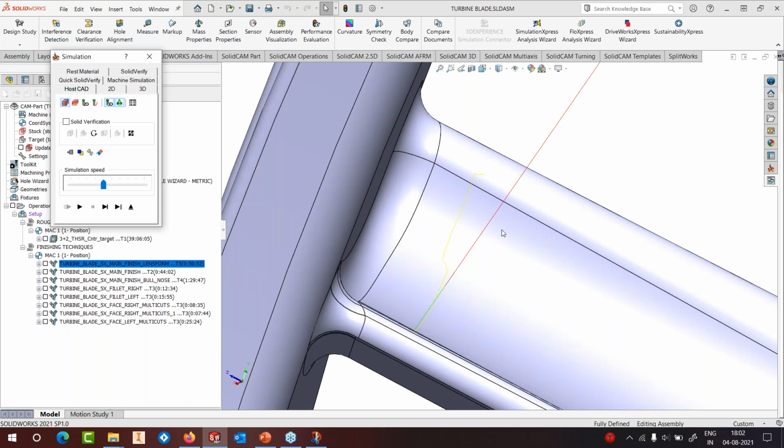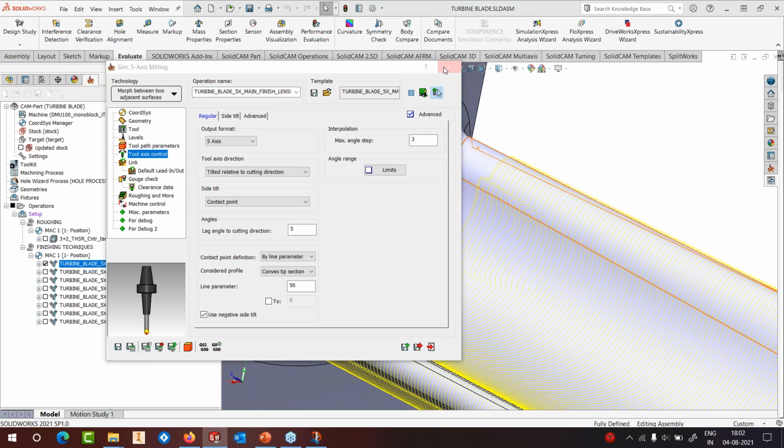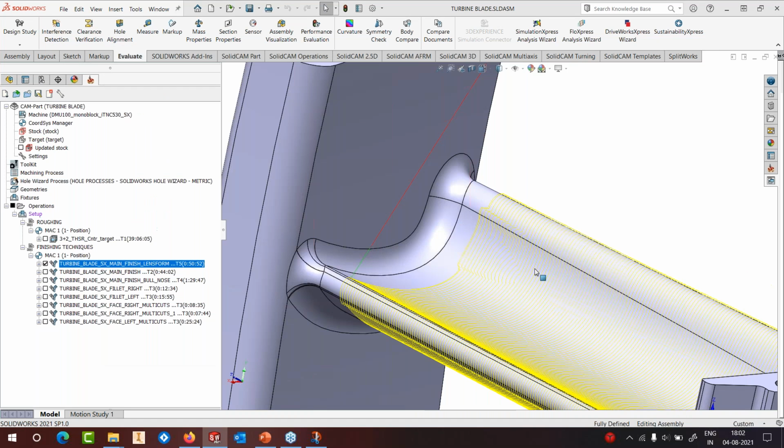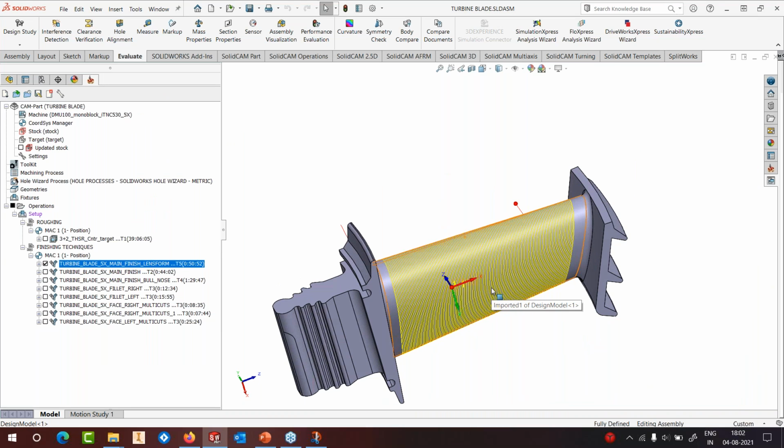And look at that, that's crazy. We have a toolpath here. So this is how the toolpath gets generated. I can give a bigger step over. I would have normally given about 0.3 millimeters here if I was using a 16 diameter ball nose tool, or even a 16 corner radius 2 or 3 millimeters bull nose. I would have given about 0.3, but here I've gone up to 1.2 millimeters step over. So straight away my machining time comes down dramatically.